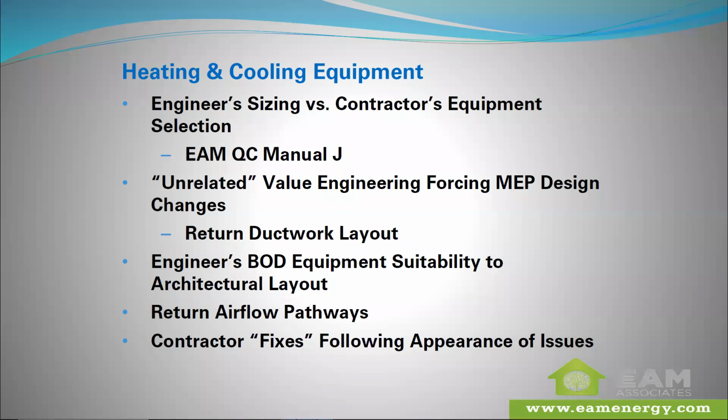One of the issues we're going to look at is the engineer's sizing versus the contractor's equipment selection. I will say that we're not going to let the engineer completely off the hook here. We did a QC Manual J on the apartments, and we found the engineer's sizing was good. They have some other things to answer for that we'll look at, but their sizing was done in accordance with the ACCA manual, so that was correct.